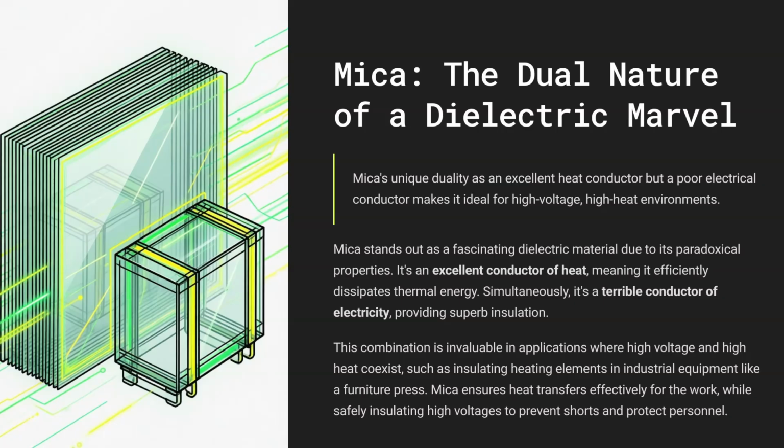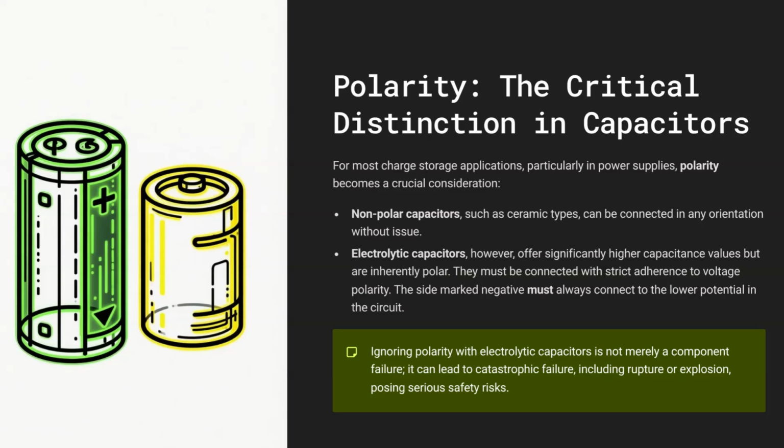That makes sense. But for most charge storage applications, like in power supplies, we hit a really critical distinction: polarity. Right. If a capacitor is nonpolar, like a ceramic one, you can connect it any way you want. But if you need huge capacitance values, you have to use electrolytic capacitors, and they are inherently polar. They have to respect the voltage polarity. The side marked negative must go to the lower potential in the circuit, period. And if you get that wrong, it's not just that the component fails, it fails violently.